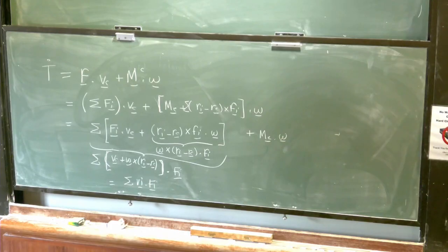For the bar on its own, what are the forces acting on it? The spring force. This is an extended spring. And the reaction force at O. And the weight. Spring force and weight are conservative. Reaction force at O is workless. So is energy conserved? Yes. Okay, what else do we have? Problem 4, is energy conserved?